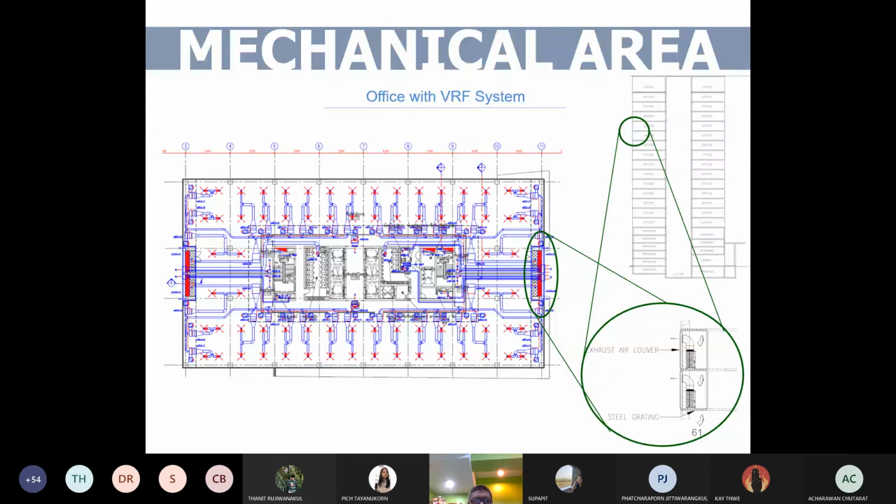So it depends on how you charge the tenants or the people in the room. If they are charged by the hours of operation of the fan coil, I 100% recommend using VRF because you can make a profit of at least 20%. I see. But anyway, students have to prepare a kind of balcony for putting the condensing units with access in their design,